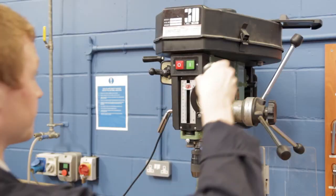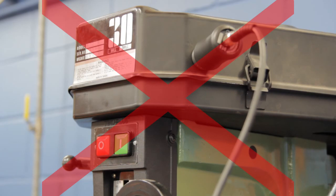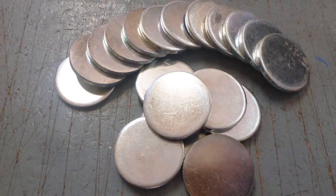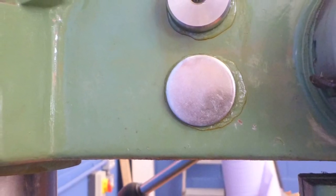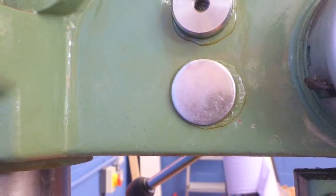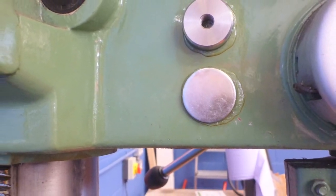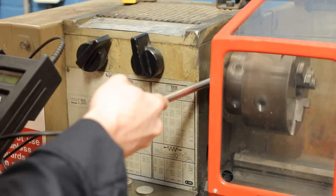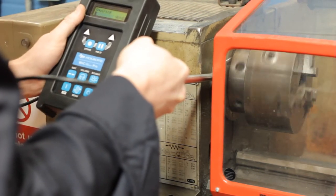The sensor should not be placed on loose covers or guards that are not directly connected with the source of the sound. Once a suitable place of measurement has been located, a galvanized steel pad can be bonded in place. This ensures that the measurements are taken from the same position each time, thus increasing repeatability. These pads also provide a flat, smooth surface to take a measurement on. Extended probes can be used to take measurements in difficult-to-reach locations for both standard and slow mode.